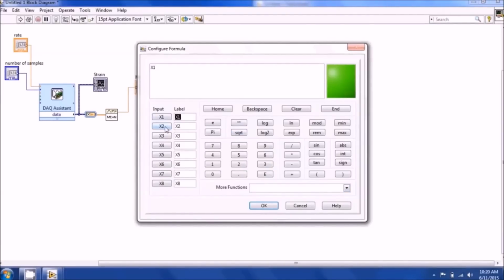So what we're going to do is insert variables for weight, LS, strain, base, and height. Now when you do the measurements of the base, height, and LS, do it all in metric units. So we're going to have mass because we're going to convert that to weight. You have LS, you have E, you have base, and you have height. So the equation is 6 times the mass, but mass is only in kilograms, so we need to convert that to newtons to be a weight.